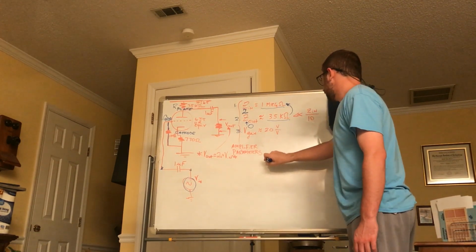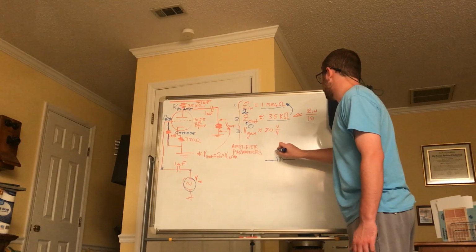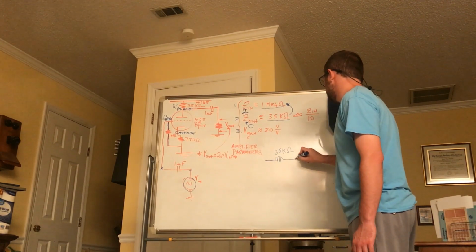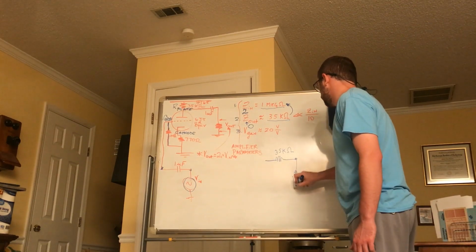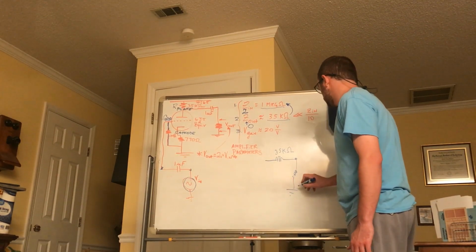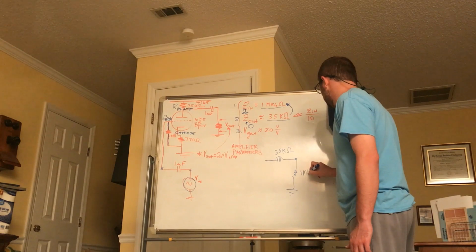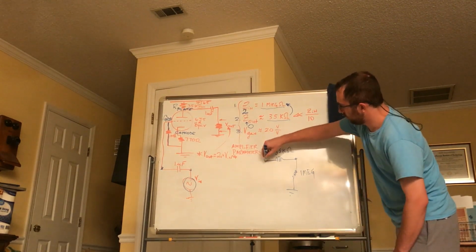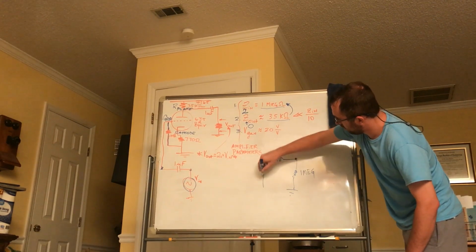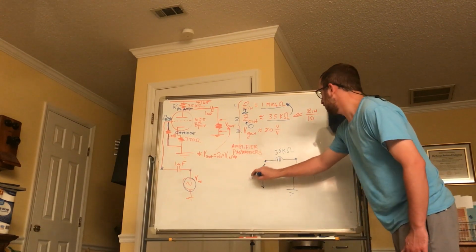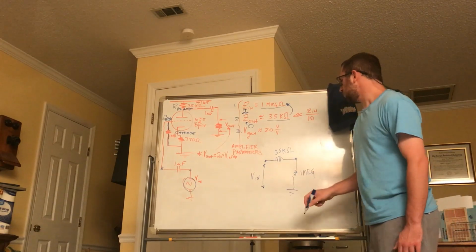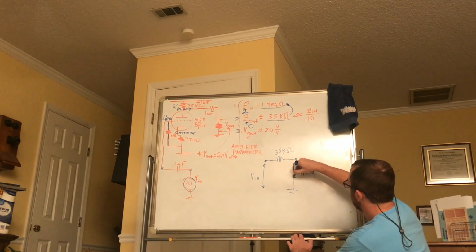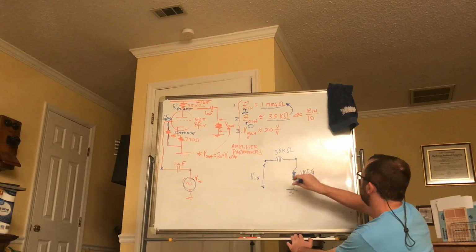In other words, what you can do is you have your 35 k ohm output impedance, and you're trying to hook that up to another amplifier, and that would give you 1 meg. In other words, by the voltage division rule, most of the voltage applied between here and here, which we can call Vn, will show up across the 1 meg, which is what we want.